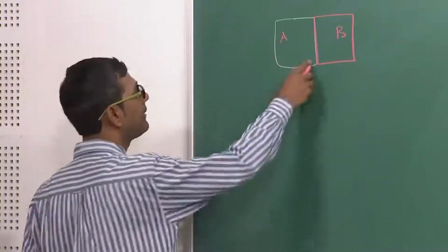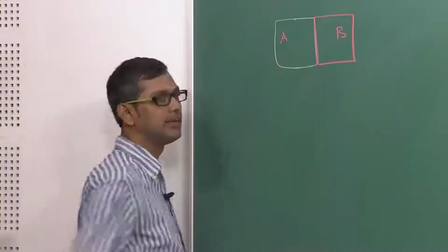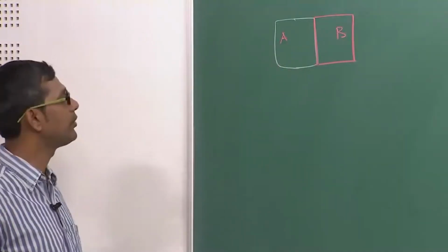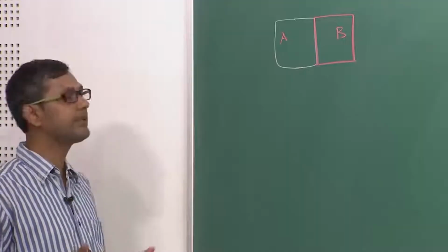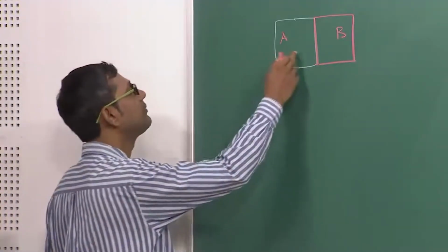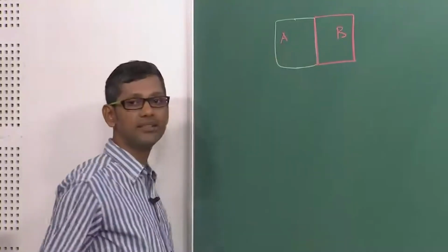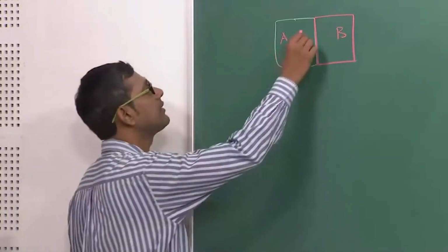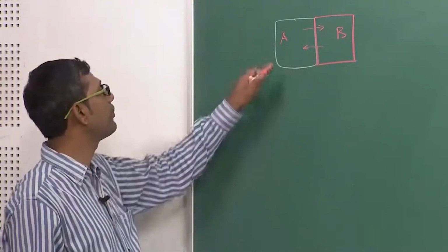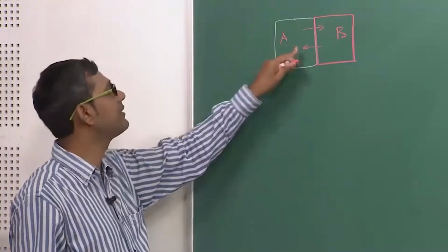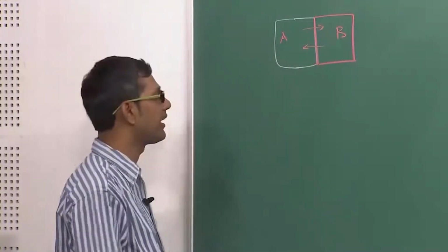That is why there is a white and a pink color line. So, this is welded. Now, I take these two joint pieces at a high temperature. So, the moment I keep it at high temperatures, atoms here will diffuse to this side, similarly atoms here will diffuse to this side, because there is a compositional difference. Okay. So, obviously diffusion will happen through this interface, because the composition in A is different from the composition in B. So, because of that there is a gradient automatically.